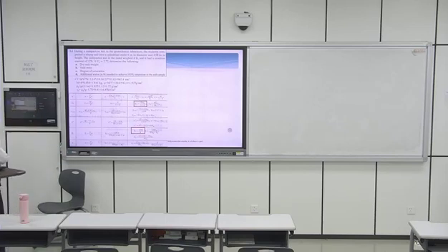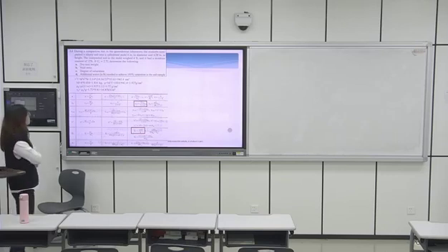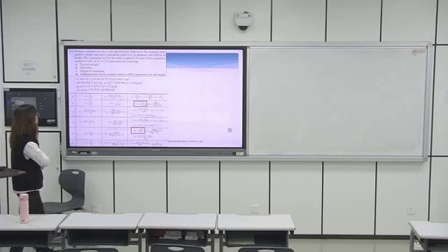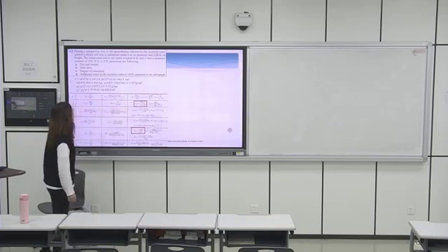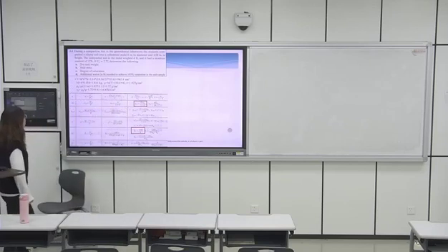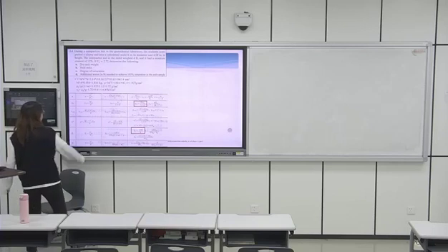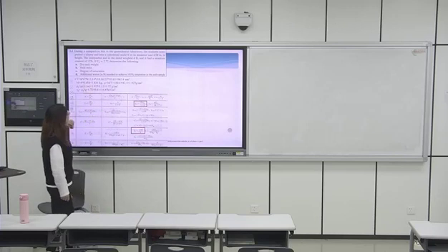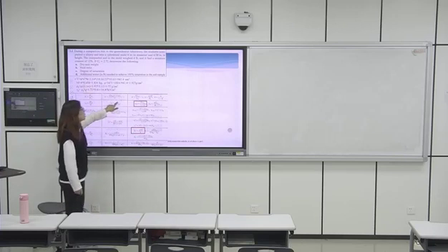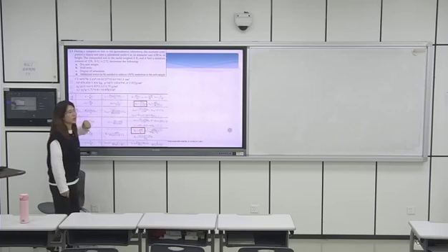The first 3 are very easy because we have this table, right? First, let's see the dry unit weight. If you want to calculate dry unit weight, you can use this, or you can use the other method, right? But here, what do we use? For dry unit weight, we actually use the method I gave here, this one. If we want to use this, the water content, we know it is 12%. We know the water content. And we need to know the moist unit weight, gamma, right?